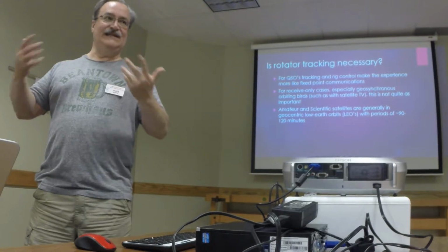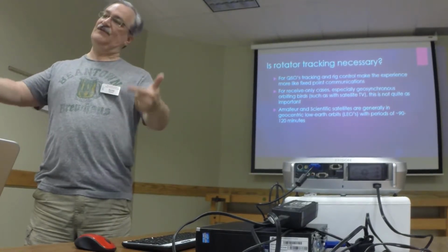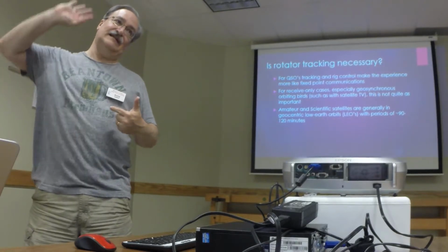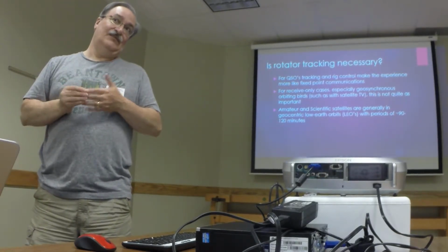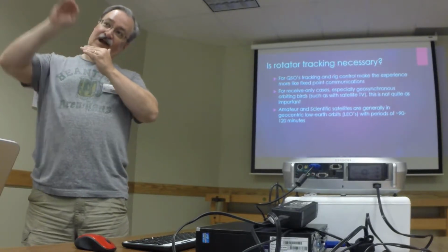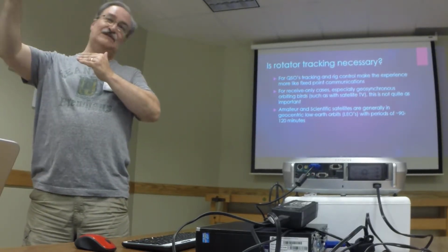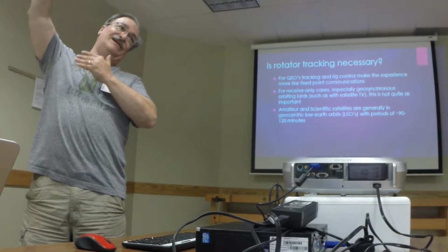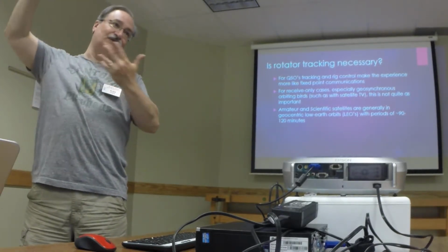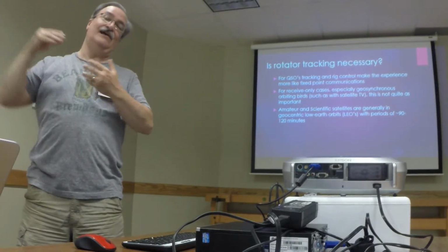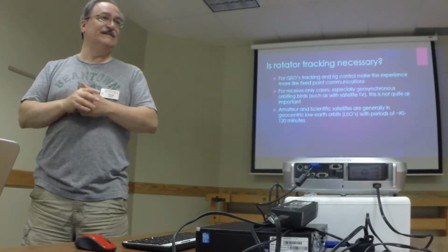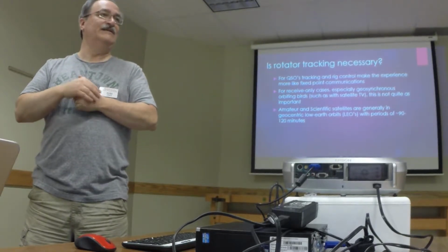Because again, the power part is easy, so you have to essentially have the preamps there to be able to pick up from the satellites that are some distance away. Because if you think about it, they're not just line of sight or around the curve of the Earth 1,000 miles away, they're also in orbit. So if you look at what kind of distance you've got to traverse, even though there's really nothing in the way per se, other than the atmosphere, it's still a fair distance. And at those frequencies, it takes some power to go a distance like that.